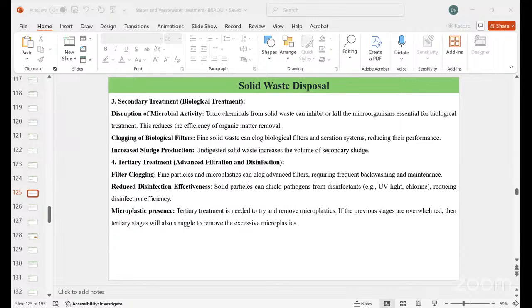Coming to the type 3 waste, which is defined as garbage, consisting of animal and vegetable waste from restaurants, cafeterias, hotels, hospitals, markets, and installations. This type of waste contains about 70% moisture, 5% incombustible solids, and a heating value of 1390 kilocalories per kg as fired.